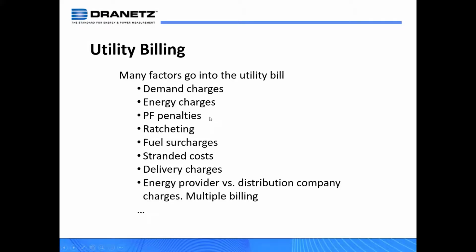So you will get a surcharge from your utility if your power factor exceeds a certain limit or goes below a certain limit, maybe 0.85, 0.7, 0.8, whatever it may be from your utility. And this is where you may want to have some power factor improvement or power factor correction. We have some very funny case studies that we share during our seminars where the built-in power factor correction is offline in some of the facilities and they don't even know it.